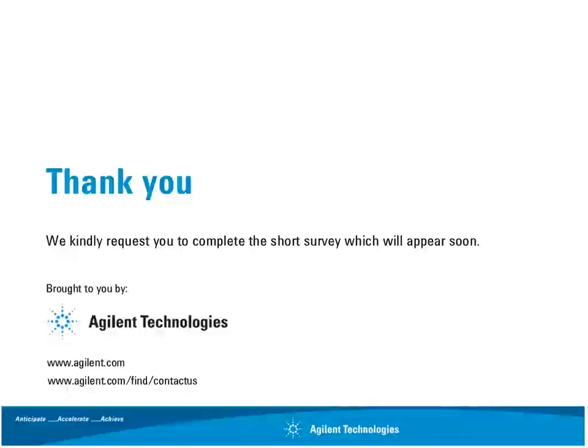Okay, great, thank you. And Scott, I've got a question for you here. How does resolution bandwidth determine the sweep time? As you reduce the resolution bandwidth, your sweep time slows down by the inverse of the resolution bandwidth squared.